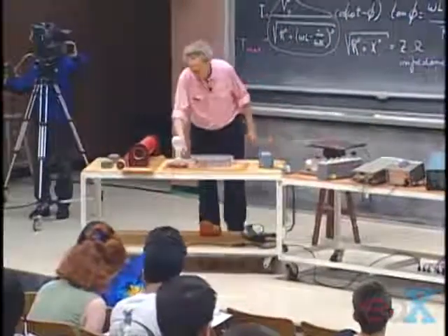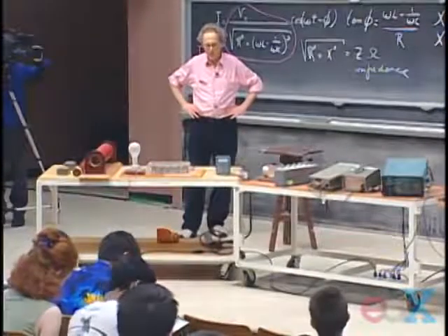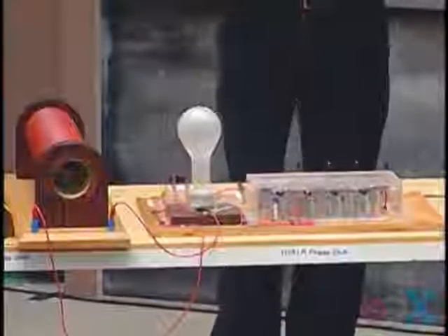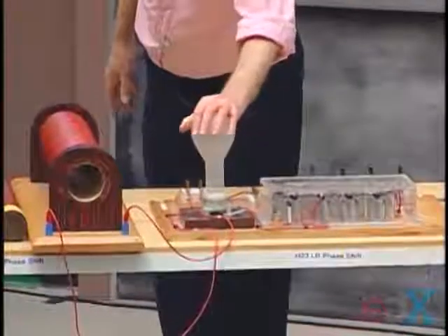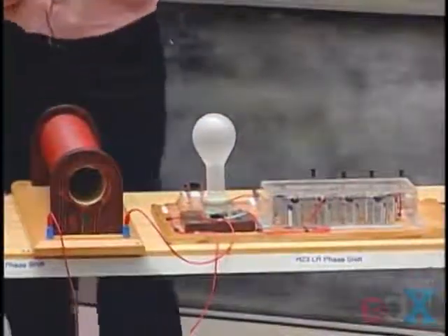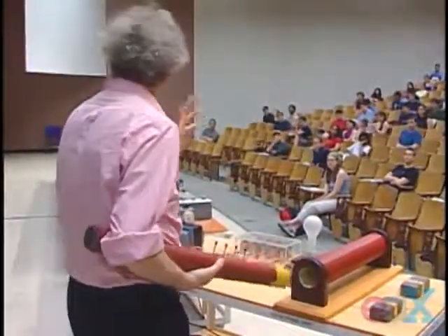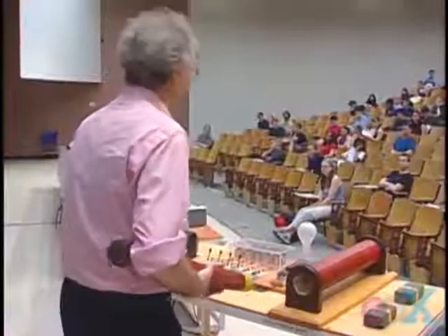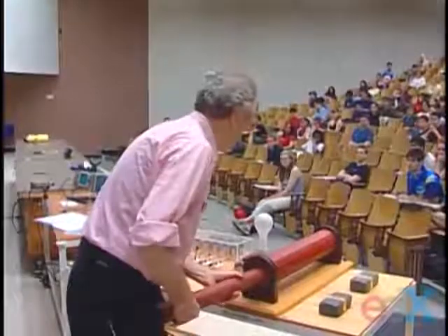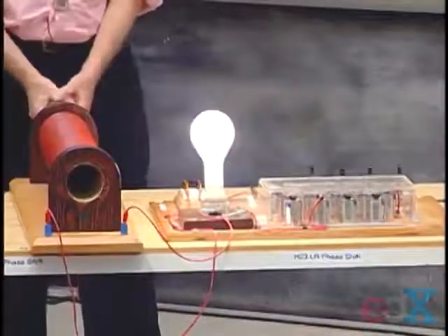All right, so here, system is now, current is going. 60 hertz, 110 volts, root mean square as we call that, and it's way off resonance, 7.5 watts, the light bulb doesn't even feel warm. And now I bring this enormous piece of iron in there, and when I shove it in, the self-inductance will slowly go up, the resonance frequency will shift, and the current through the system will increase. And there we go. There it is. I'm on resonance now. So the light bulb is quite happy.